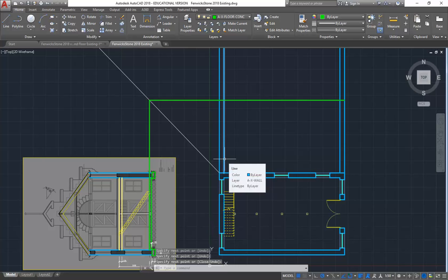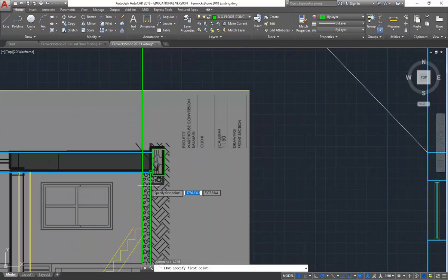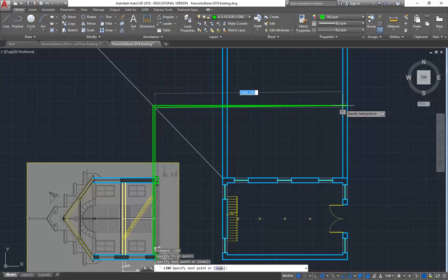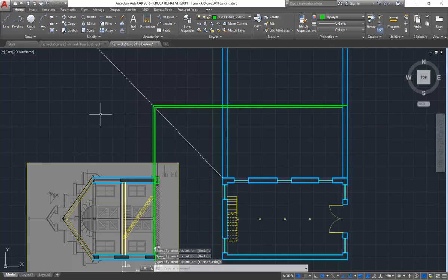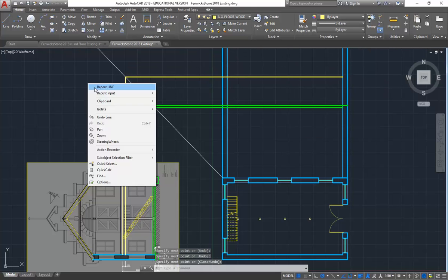and they line up. So I'll just continue that to draw a few more so it's clearer. I'll draw another line now from the bottom of my floor, again up to that diagonal line, and then across. So now maybe I'll go to my timber layer. So this is a technique you can use when you are doing hand drawing as well.